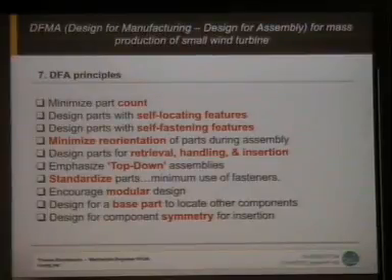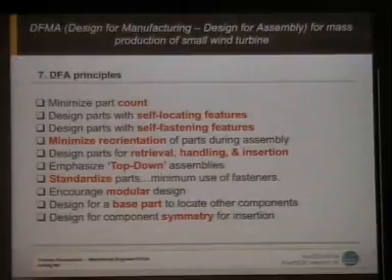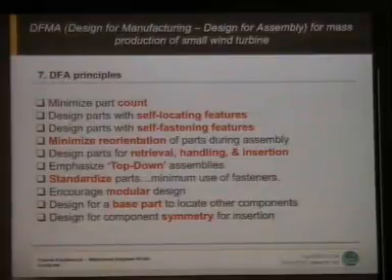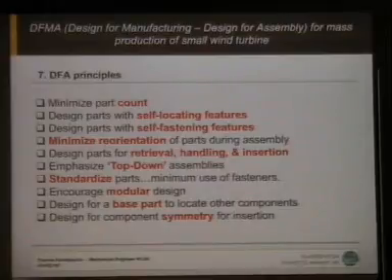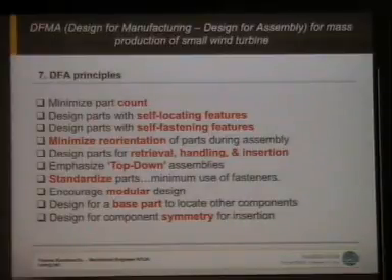Emphasize top-down assemblies, standardized parts, and minimum use of fasteners, which means it's better to use parts that you can find very easily and that are not original equipment or the like. You have to encourage modular design, and design a base part in order to locate other components, which is basic for the assembly. All parts have to be symmetrical. That's the principle.